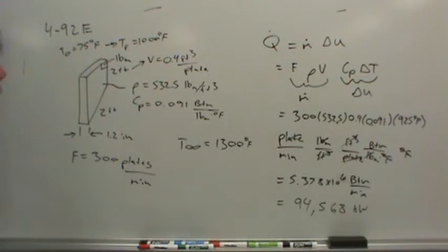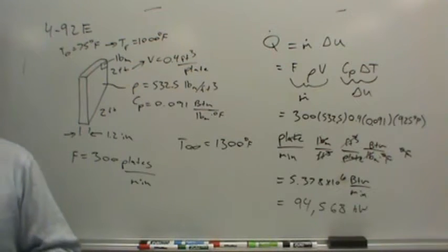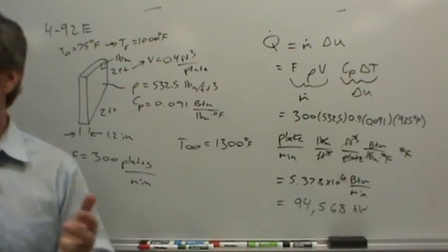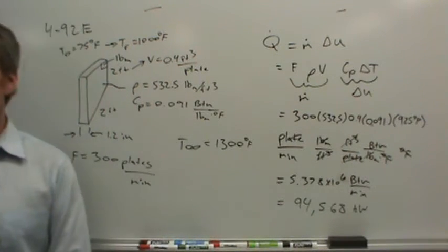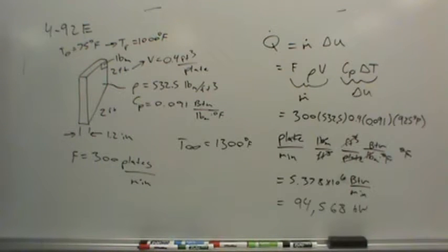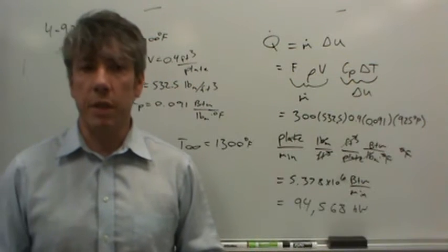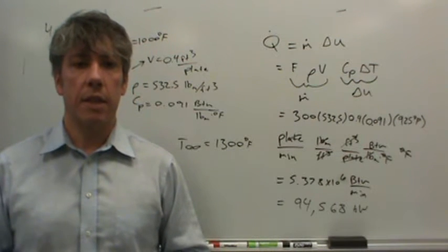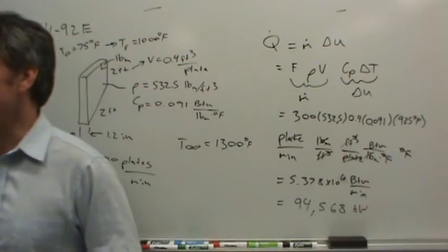So punch 95,000 kilowatts into your calculator. And let's say that we're just producing for 8 hours a day. Average month, let's take it to be 30 days. So 8 times 30 would represent the number of hours that we let this system run in a month, right? So multiply 95,000 times 8 times 30. What do you get? Almost 23 million. Fortunately, electricity only costs about 10 cents per kilowatt hour, so multiply by 0.1. How much money are we talking about? 2.3 million per month. Oh, well, we can run 2 of these factories at that price, right?